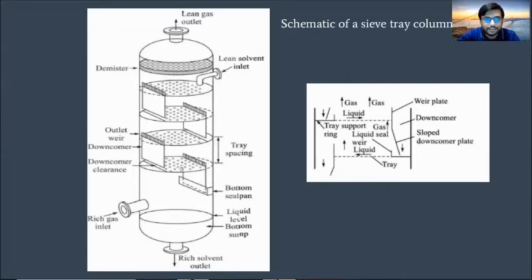And here, in each tray, there is a vapor liquid equilibrium that is established at each tray, at which the mass transfer takes place. The vigorous bubbling of the gas makes the conditions very turbulent on the top of a tray, which increases the mass transfer coefficient, and hence favors the mass transfer between the gas and the liquid.